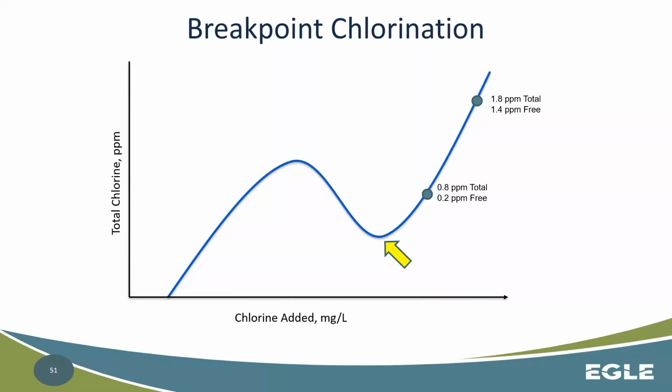Chlorination has a break point. So a lot of people think when they're getting complaints around taste and odor issues with chlorine that, man, they need to back that chlorine off. Well, a lot of times this isn't necessarily true. It's just the opposite that needs to occur.